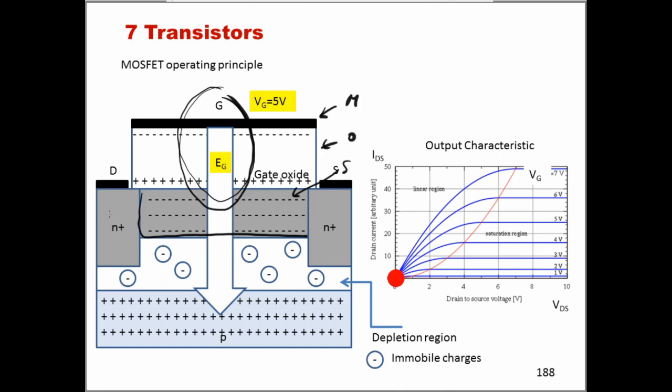So we have the drain n-type, the source n-type, so they both have a lot of electrons, and now there is a region that is also effectively n-type, because we have created an inversion region there that is bridging these two together. So effectively we could say that now we have created a channel. This source and drain are connected now.